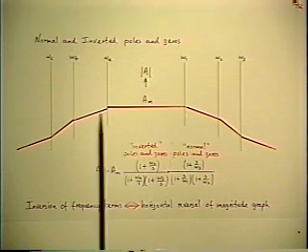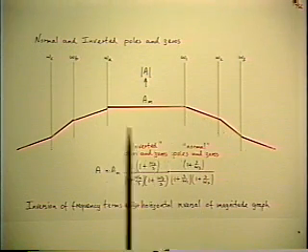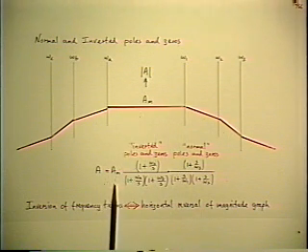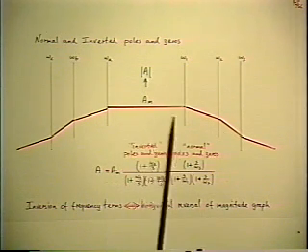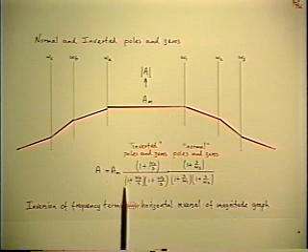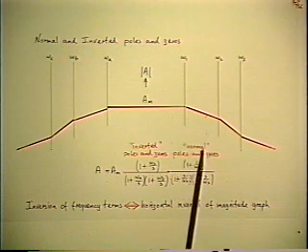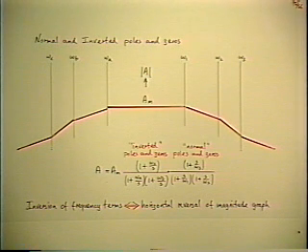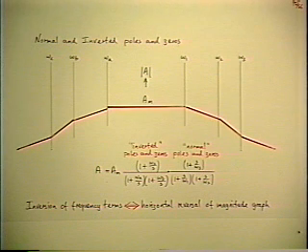So here's a frequency response with one flat gain. Take that as reference by writing it in front. And now when you look down in frequency, you have the inverted poles and zeros. When you look up, you have the normal poles and zeros, and they're all there together. Okay. All the examples so far, we've had one flat gain.